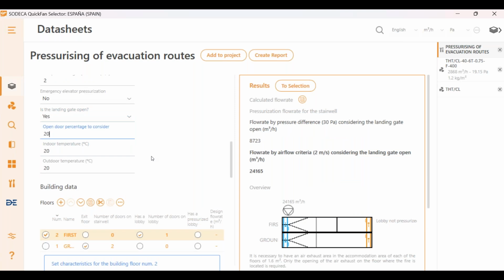I would like to mention that our Kitbox PDS Smart includes a system that, reading the pressure evolution in the staircase, is capable of knowing if this final exit door is not able to be closed. When we detect this situation, with the final exit door not closed due to the residual pressure differences in the staircase, for a very short period of a few seconds we reduce the capacity of the fan to reduce the overpressure in the staircase, and to allow the self-closing mechanism to close the door.